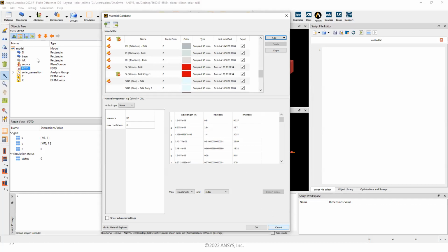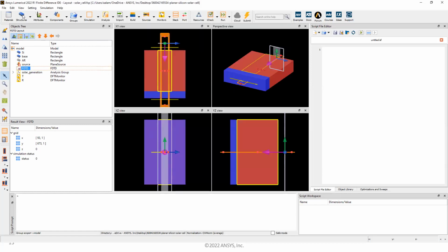And the next step is the structures. The way you create your geometry in FDTD is by combining smaller blocks to create a complex geometry. So you have primitives like triangles, rectangles, polygons, circles, and so many other types of primitives. You put them one by one in your design tree here, and then those things combined will create this structure. Here we have a very simple structure. We just have a silicon slab, and then we have the metallic base at the bottom.